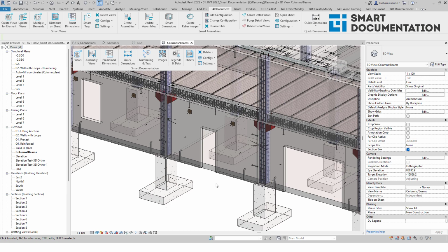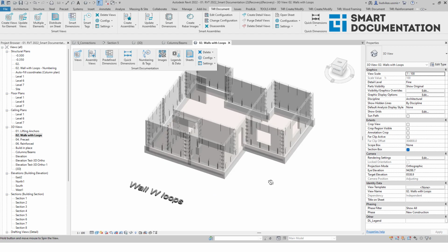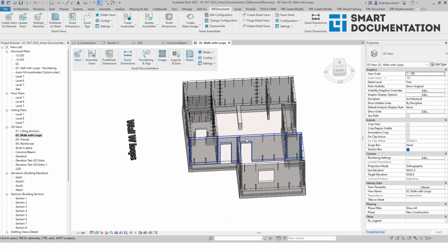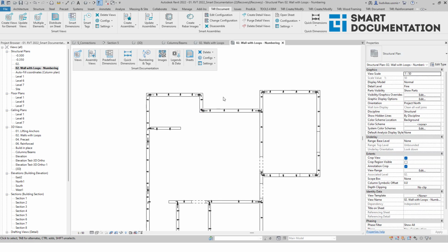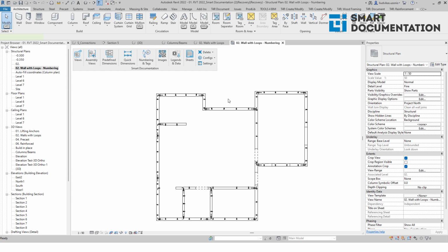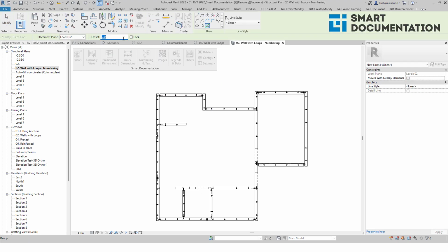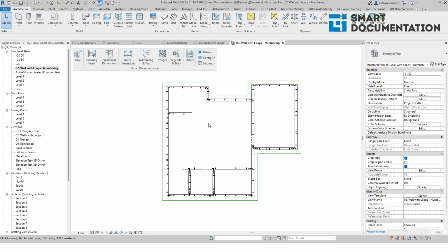Or I actually have one more sample, and I'm going to open a different model, this one. So I have a simple structure, and I have these wall elements, right? I'm going to switch on the floor plan. Here, I want these elements to be marked according to my model line. So I'm going to place a model line, offset, and okay, I need to snap to this. Right, so now I have this model line.